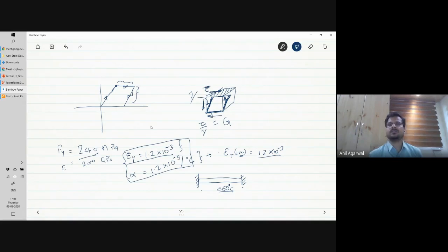So for example, when we are designing a tower or a building and a beam wants to expand, it is not really subjected to fixed boundary conditions at both ends. It is supported on columns, and columns have some kind of flexural flexibility. So when the beam wants to expand, the columns let it expand a little bit. Similarly, you have a tower. Members of the tower want to expand. They can expand. Nobody is stopping them. The tower will become like 0.12% taller after a 100 degrees centigrade rise, but who cares, right?